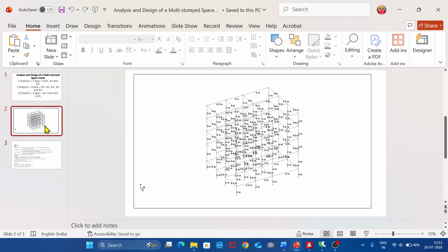If you see the diagram, this is the ground floor and this is the roof slab of the ground floor, and likewise it will go to the floor slab, and in the topmost we have the roof slab. The slab starts here, so 2 meters is from the footing, so 2 meters plus 4 meters, the ground floor height including the basement, so 2 plus 4 is 6.